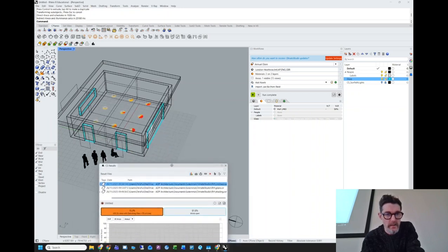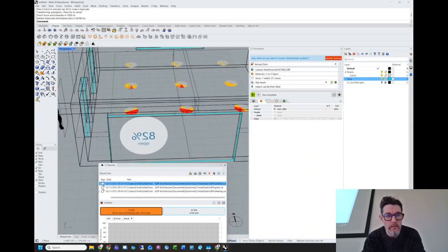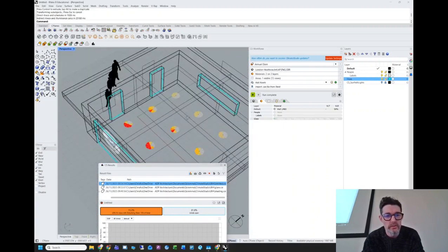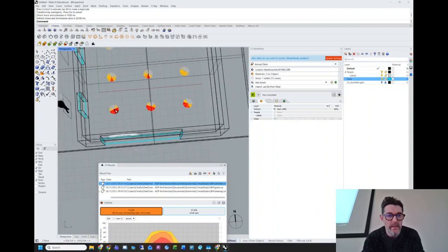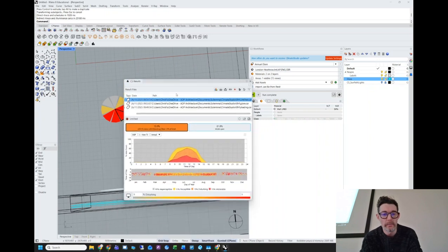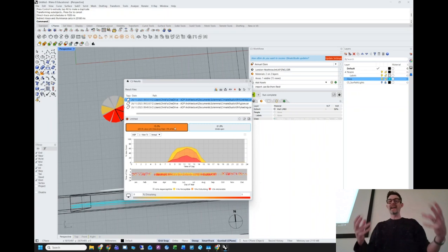What it's saying to me is it's put these little pizzas all over my thing here, which is to identify basically that in this location, if you're pointing in this way or this way, you're probably fine. But if you're pointing towards the window, then what you're looking at is basically over 12% of your time, in fact 15.3% of the time in the year, the glare in that place is intolerable. It's like trying to work in a greenhouse. Your eyes will just not thank you.